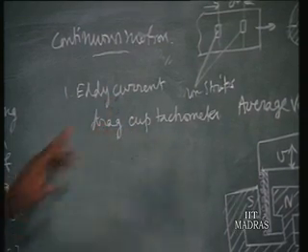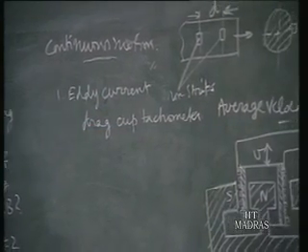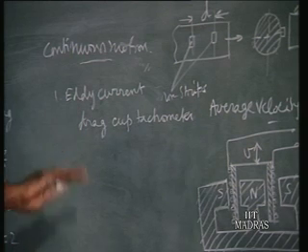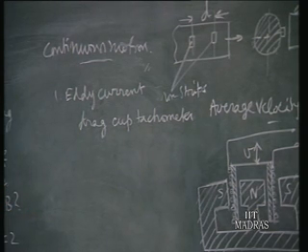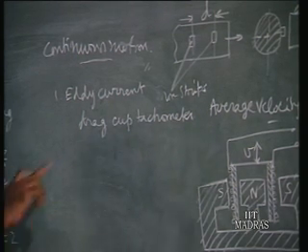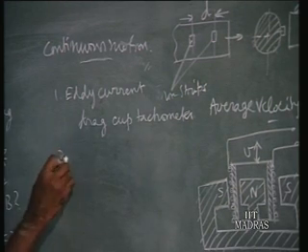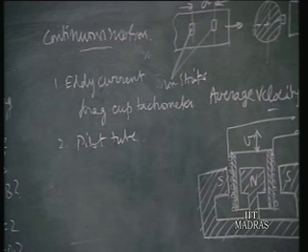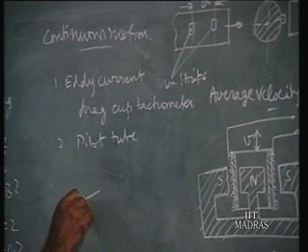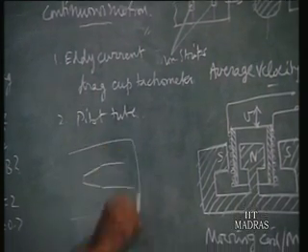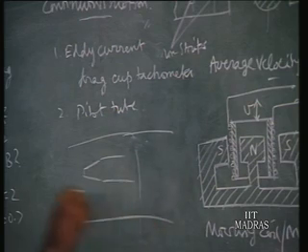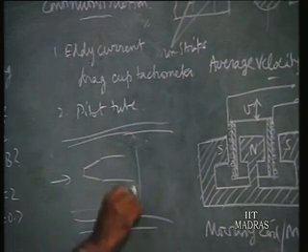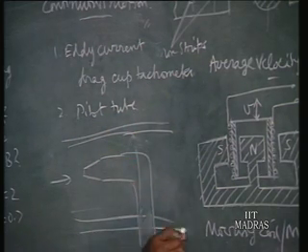This is essentially a rotation measuring instrument which is calibrated in terms of kilometer per hour by considering the circumference of a wheel. Then second we have got the pitot tube for the vehicles, so aeroplanes as well as ships on the sea, we can also use a pitot tube. You know, a pitot tube is used in pipes to measure the velocity of fluid in a pipeline. So, this is a pipeline where it is fixed.